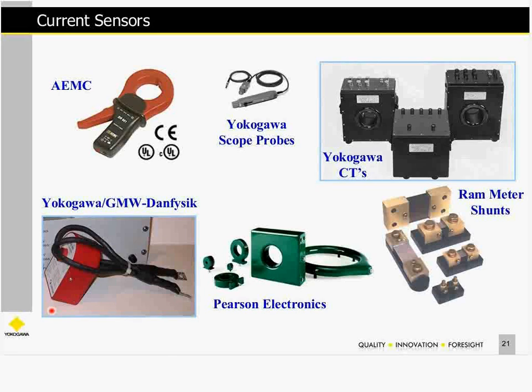It's a whole different type of technology they call the zero flux technology current transformer, and a system that we developed together with Dan Physics, which is now part of LEM, and this provides some real interesting applications from DC up into the hundreds of kilohertz area. Very high accuracy, from like 0.05, 0.02% of the full scale. So we have a lot of current transformers that we can help you with your application.